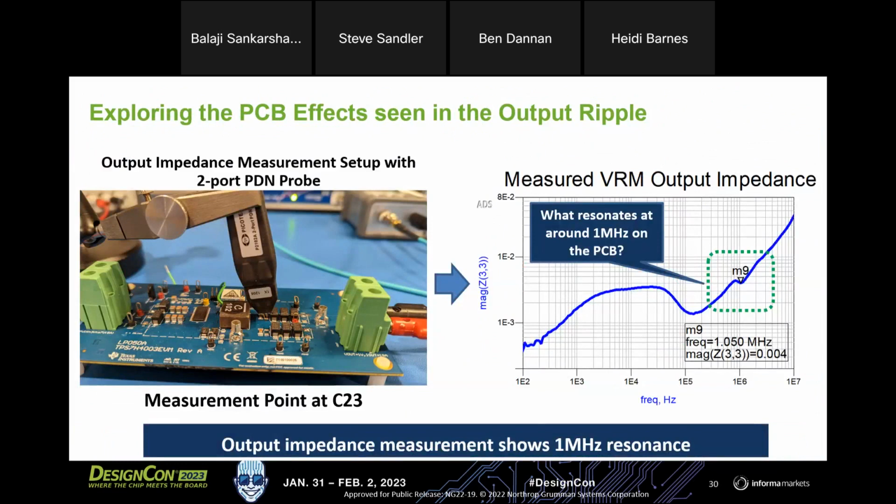And if you go on the Picotest website under the solutions page, there's a lot of stuff measuring PDN impedance. But essentially, it's an AC Kelvin measurement. And here you can see Ben showing the probe that he used to make the measurements. It's one of our two-port probes. And this probe actually has 4 tips on it, 2 grounds, 2 signals, and we're doing a force and sense measurement using a vector network analyzer.